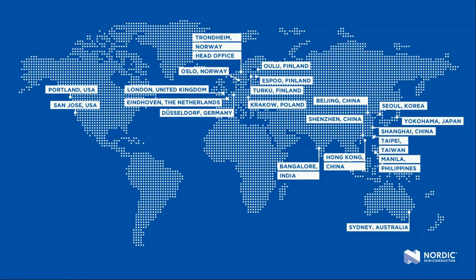And then there's a question whether you can still run GPS when completely turning off the LTE. That is correct. If you completely turn off the LTE, the GPS is still available and you can run it. And you can then use assisted GPS, as I talked about, in order to get assistance data to the GPS. Then you can start a GPS, and the GPS will basically go out and ask for time of week from the satellites, and you will have a fix. So that's a very easy way to get a fix.